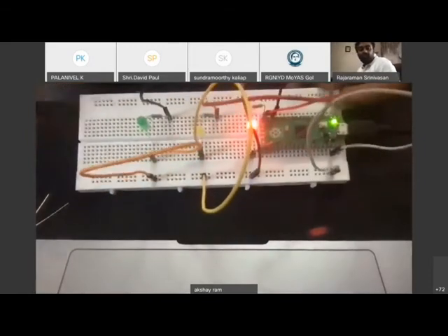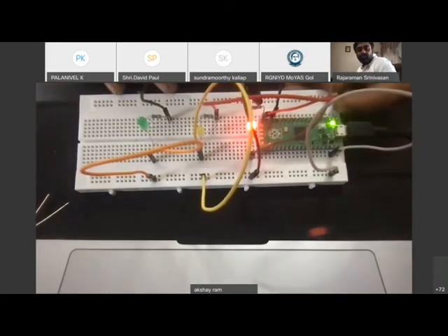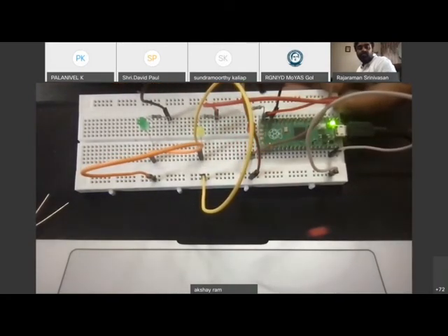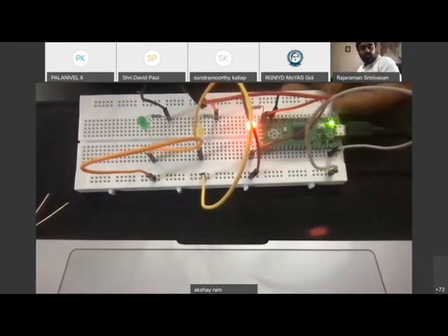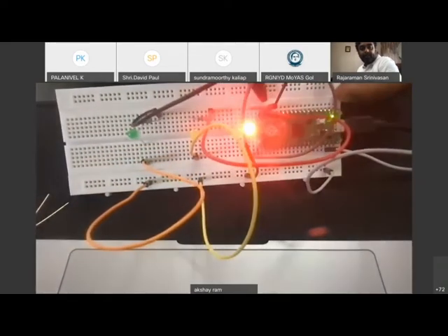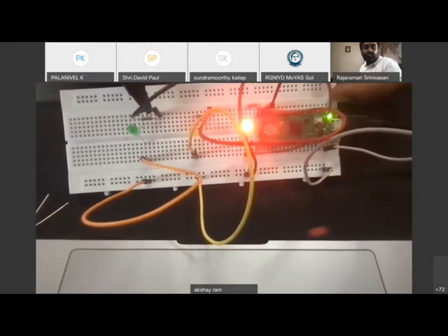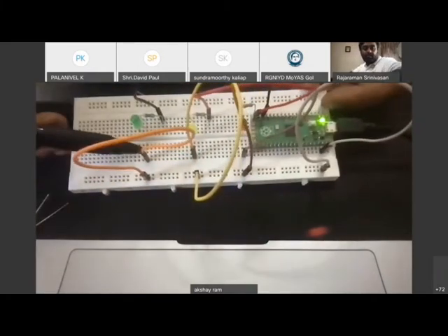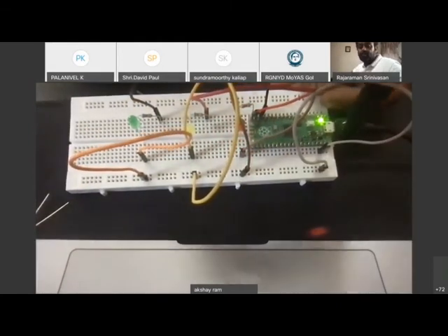So the entire setup once again, but we can do it a bit faster. So pin 15 is connected to this LED directly via this resistor. So pin 14, the red wire is coming over here, and this line of the breadboard is connected to this LED's anode by this resistor. So pin 13 is one after pin 14 because there's a ground in between. So pin 13 is connected the same way as this amber light is connected. So pin 14 comes over here, and then through the resistor it goes into the LED, and then the cathodes are all grounded on this rail, which is connected to this ground through this white wire.